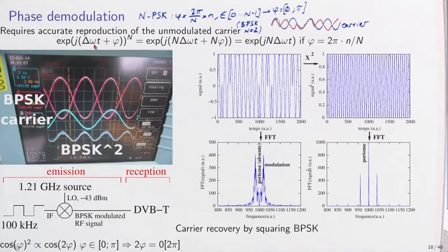Delta omega is the frequency offset between your local oscillator and the remote oscillator, and there is always a leftover. Remember, we have atomic clocks, and even if we have an atomic clock on the ground, we might always have the Doppler shift. So this delta omega is the frequency leftover between the transmitted signal and the local oscillator of the receiver, and phi is the random information that was transmitted.